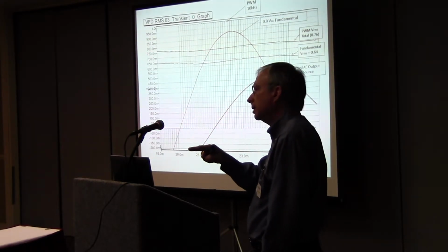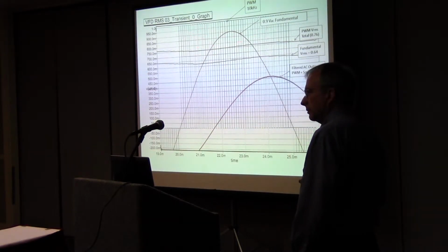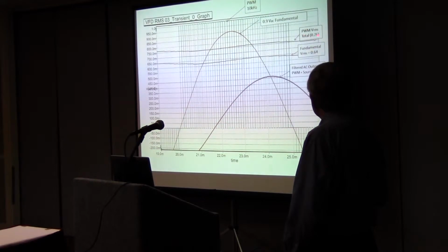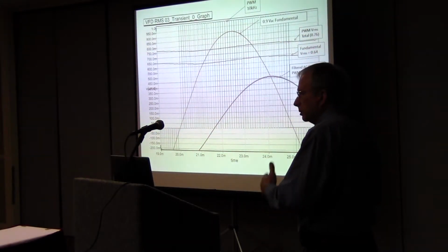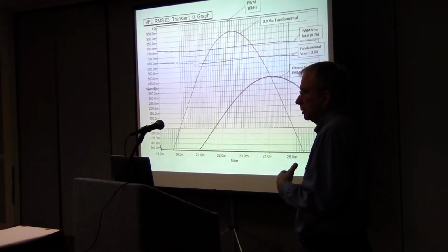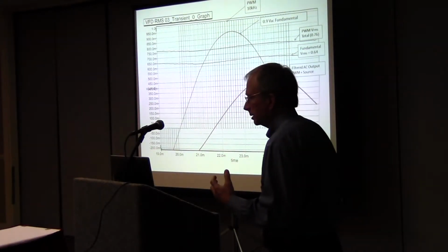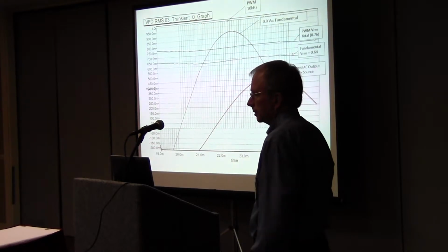Well, I'm sorry, you can't do that, because the RMS of this, which is what the voltage waveform is, is higher than the 60 hertz filtered component going to the compressor. So that's why I say you've got to know what your motive is in making this measurement to know what value you need to measure.